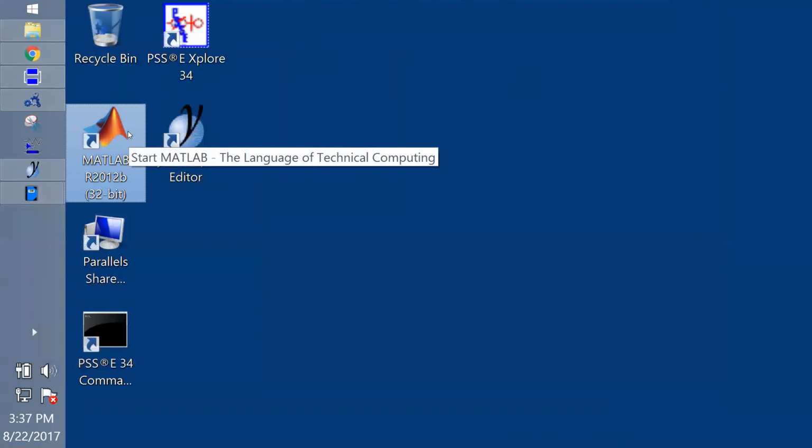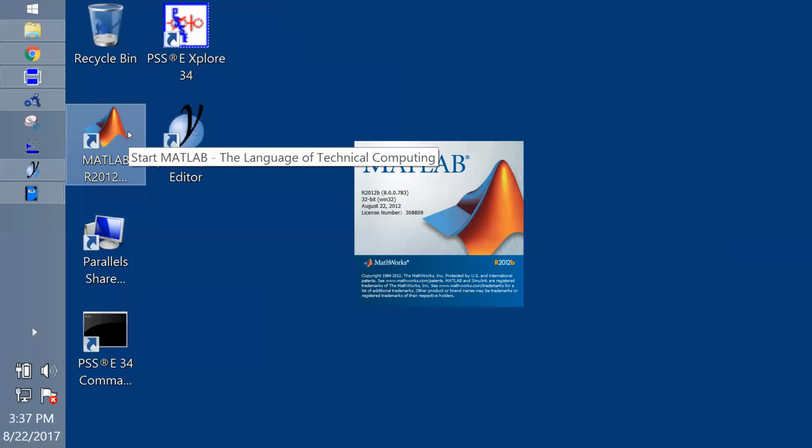The toolbox is open source, but you require a license for the FMI toolbox for MATLAB Simulink. If you have Dymola, you don't need that, because Dymola comes with something called the FMI kit. So you should already have the FMI kit under the installation directory, and that one will just import your FMU.